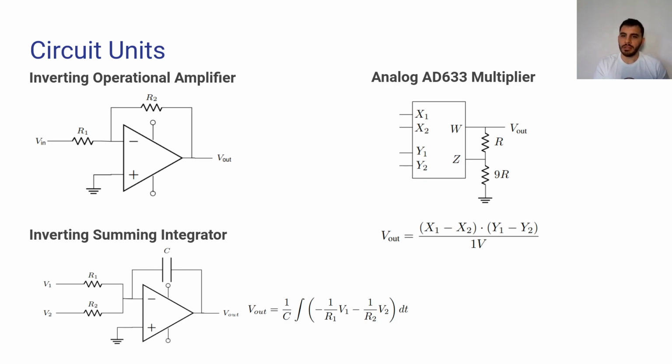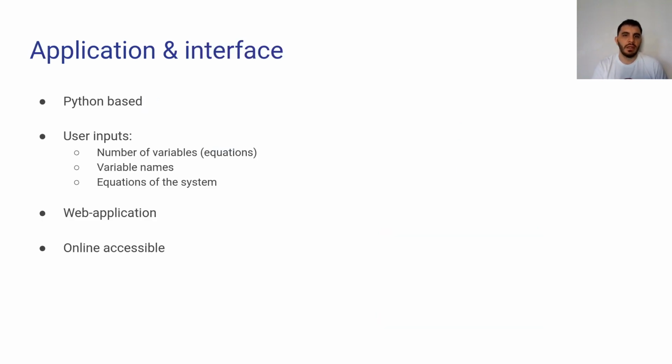And it's also worth mentioning that we can generate any sign required. So if we want a positive product, we connect them to x1 and y1. Whereas if we want a negative product, we can connect signals to x1 and y2, for example. And this is something that we use so that we generate products with required signs, thus requiring the minimum amount of inverting amplifiers.